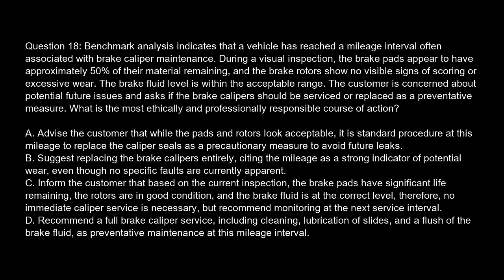Option C. Inform the customer that based on the current inspection, the brake pads have significant life remaining, the rotors are in good condition, and the brake fluid is at the correct level. Therefore, no immediate caliper service is necessary, but recommend monitoring at the next service interval. Option D. Recommend a full brake caliper service, including cleaning, lubrication of slides, and a flush of the brake fluid, as preventative maintenance at this mileage interval.